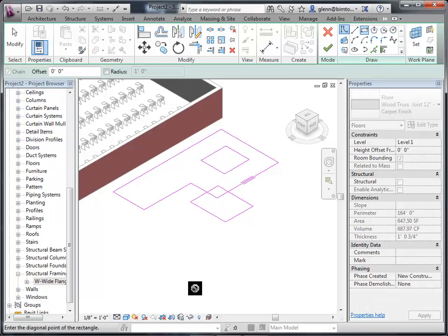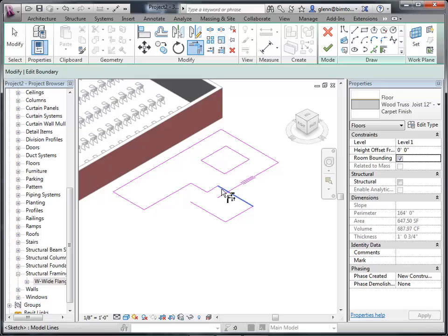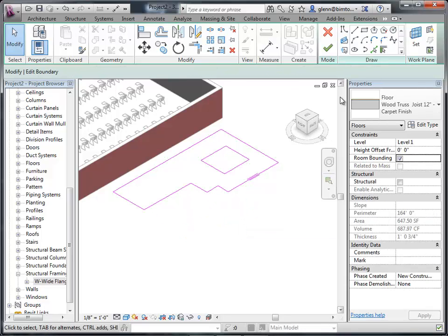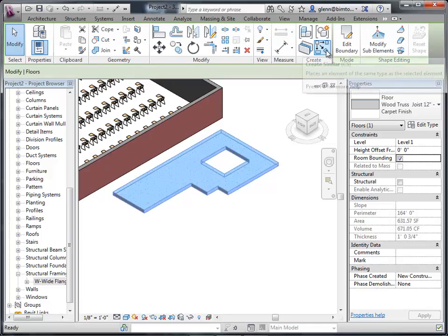This, it won't know what to do with. Okay, you can't have overlapping loops. They really have to be independent of each other. If what you really meant was nip the corner off, that's okay. We can sort of trim here and trim here. We can do some trimming to do that. But it can't handle overlapping loops. It only likes single continuous loops, so I can do this to this, and that to that. And then I still have a few extras over here, so I have to get rid of them. That'll work. But it has to be continuous loops. So just watch out for that.